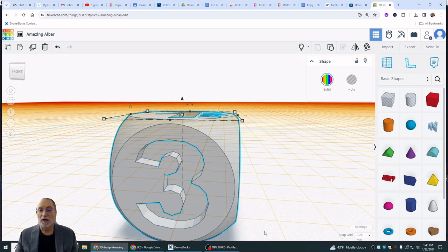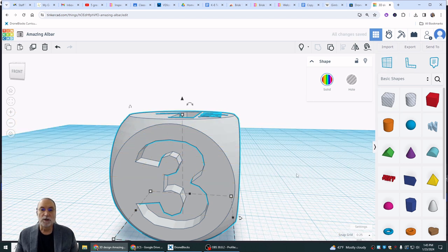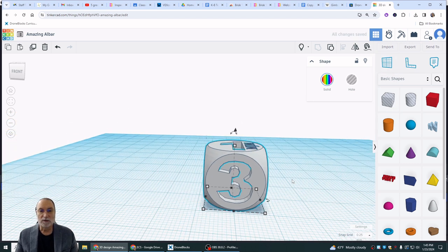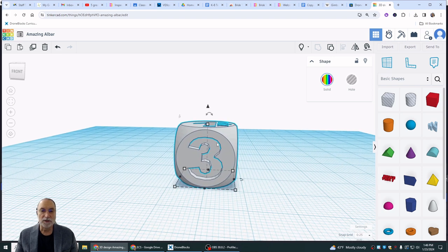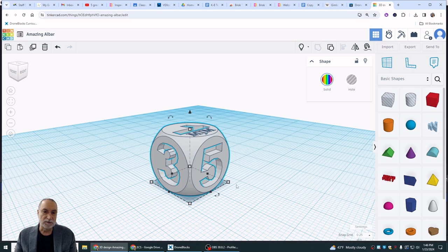And you think, we're done. Wait a minute, we're almost done. We're going to do a couple more things. So let's zoom out a little bit. Now, what I want to do is put a void. I want to put a hole inside the die. But I need to know a few things first. I need to know how big the die is. And the die is 16 millimeters by 16 millimeters.